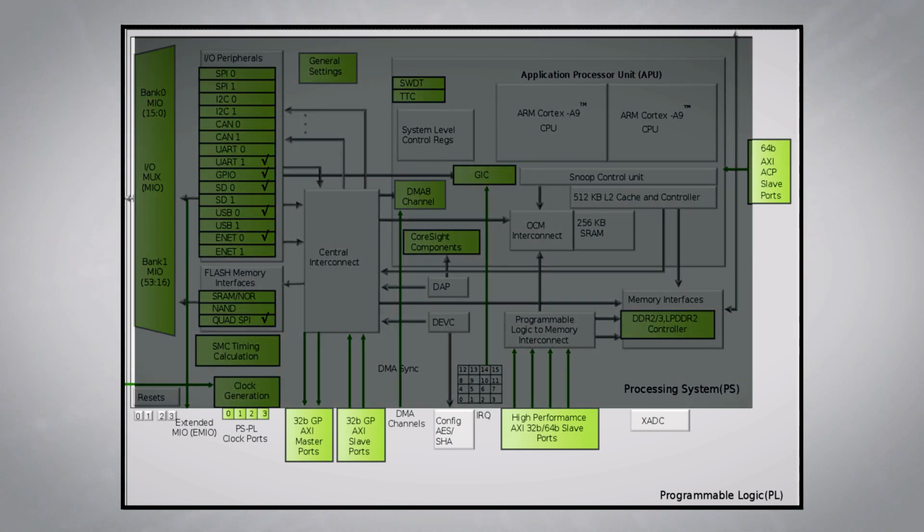However, unlike a hardcore on the Zynq and the PS, the PL is an area where you can freely create your own digital logic to expand the capabilities of the Zynq chip. If you wanted to, you can create an entirely separate CPU along with supporting components in the PL, just like in the PS, but because this is in the PL, you would have to call it a softcore instead, since you can freely modify its digital logic components. I'll place some digital logic in the PL region a little later in the video just to give you a feel for what it's like, but since we're primarily focusing on bringing up our own OS, the PS is where I'll mostly be focusing on in this video.